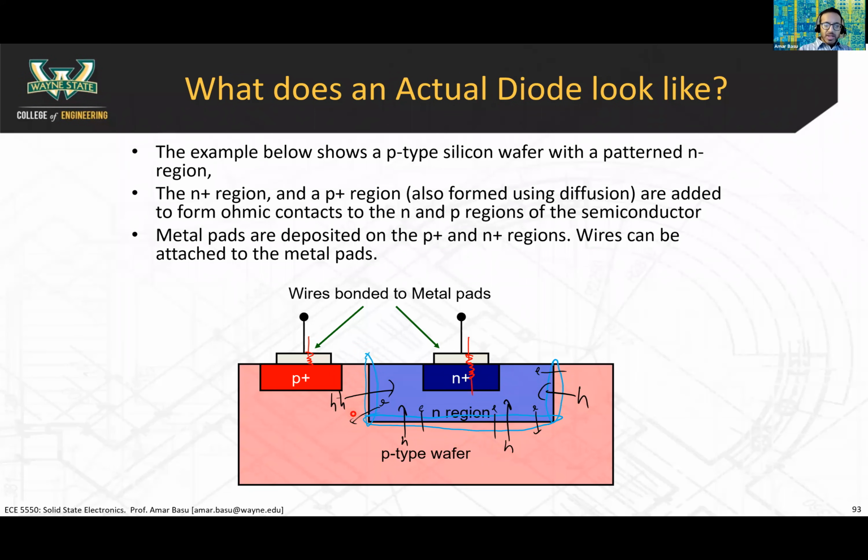So again, to sum up, the metal semiconductor contact acts as an ohmic contact, so it looks like a resistor, and then the current goes through this interfacial area. This interfacial area is where you have the diode-like characteristics, the depletion region. Then it gets into the N region, and then it flows out this contact, which is also another resistor. So the equivalent circuit for this is going to look like a resistor, a diode, and then another resistor.